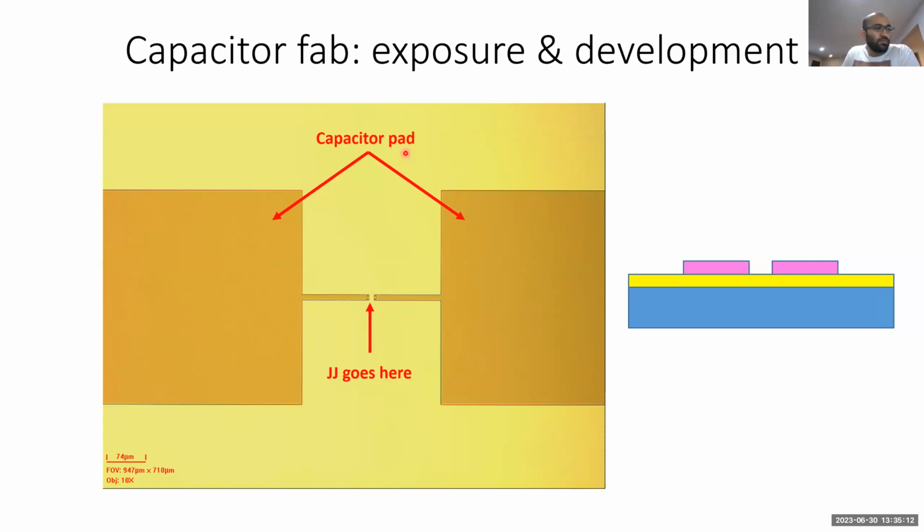In order to improve the chemical stability and chemical resistance of that resist, you can hard bake the resist. A true hard bake is done at much higher temperatures, like above 150 degrees, where the polymers in the resist will actually cross-link with each other and strengthen those interactions, making it very hard for that resist to degrade.